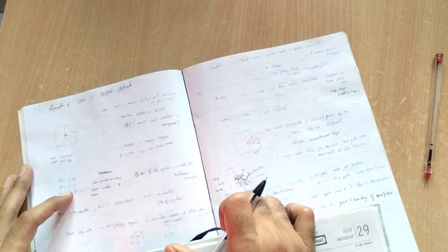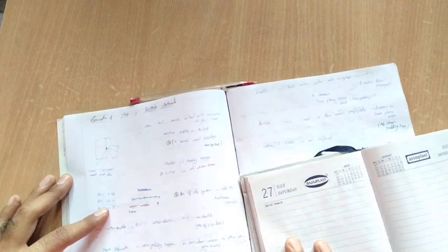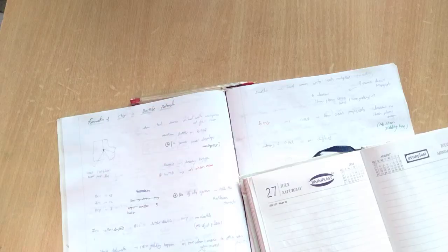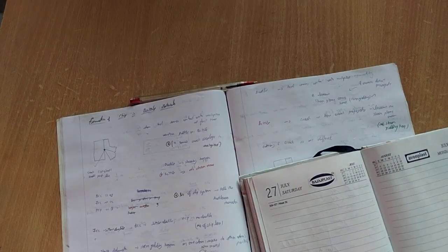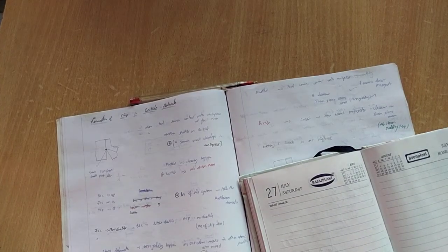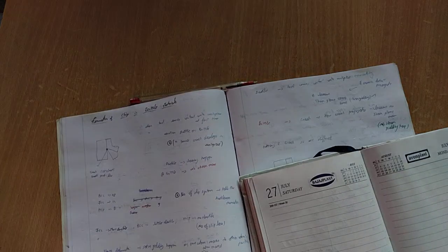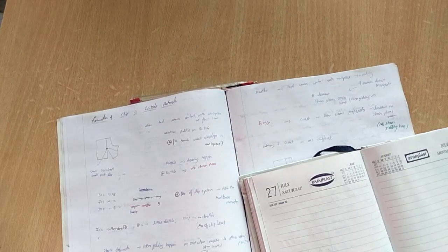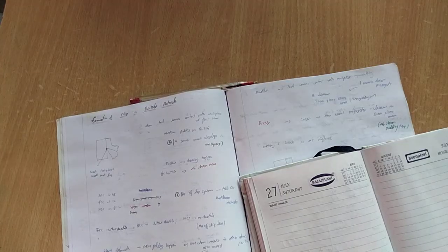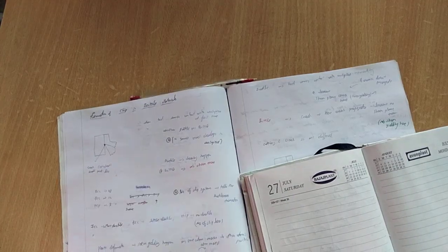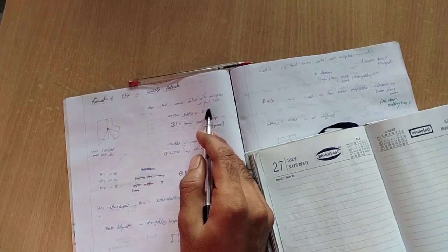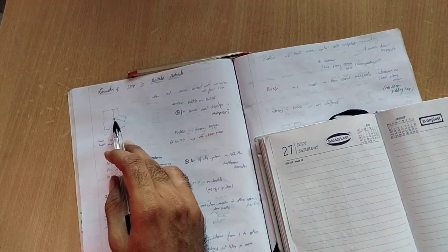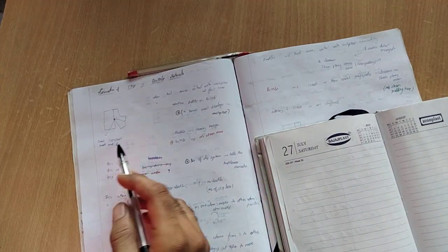So next thing you can see is the formation of chip in brittle material, okay. Whenever a tool comes in contact with the workpiece for the first time, whether ductile or brittle, a small crack is developed in the workpiece. Yes, a small crack is developed, and after the small crack, everything else is done.